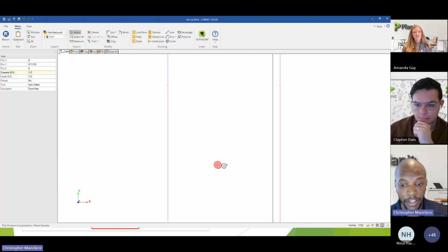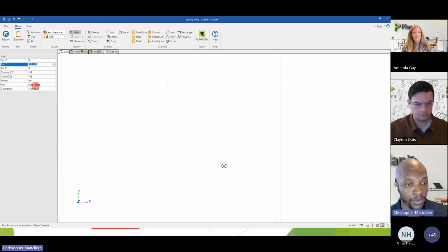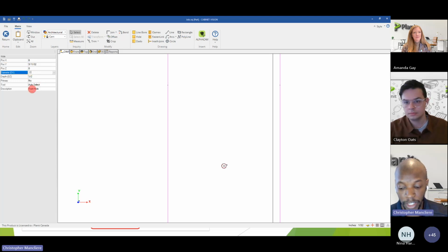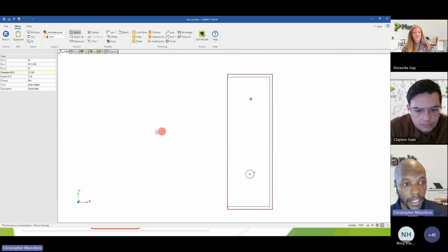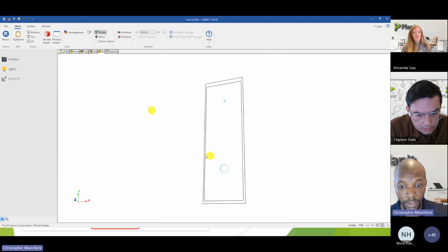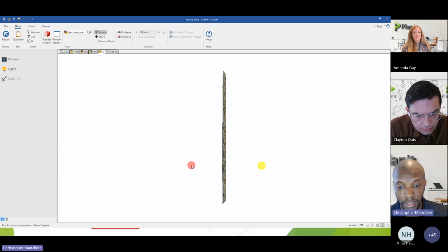So when you select an operation, you can see its properties on the left and you can change them. So you can change the diameter of the hole, you can change the depth of the hole, and also the position of the hole, as well as the tool being used for the machining on your CNC. So let's first change the diameter to 2¼. And let's also change the depth, because right now it's only ½ inch deep. So if I check, this is not going through on my part.